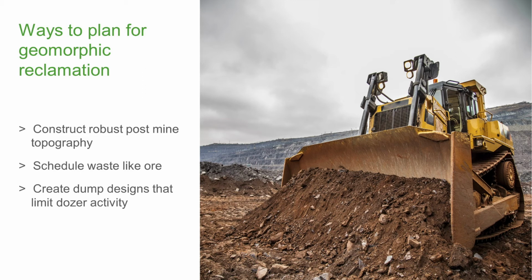This schedule can increase productivity and allow, with the utmost certainty, suitable or unsuitable materials to be handled in a correct manner. This will speed up the reclamation process and allow you to understand where your material is going. And then finally, you can create dump designs that limit dozer activity.